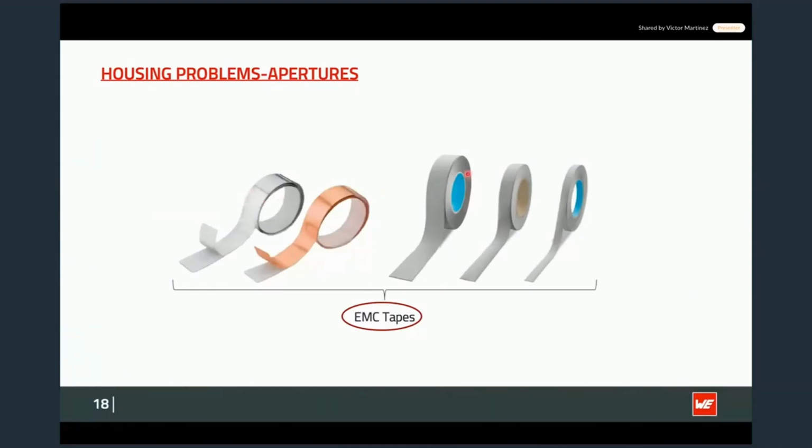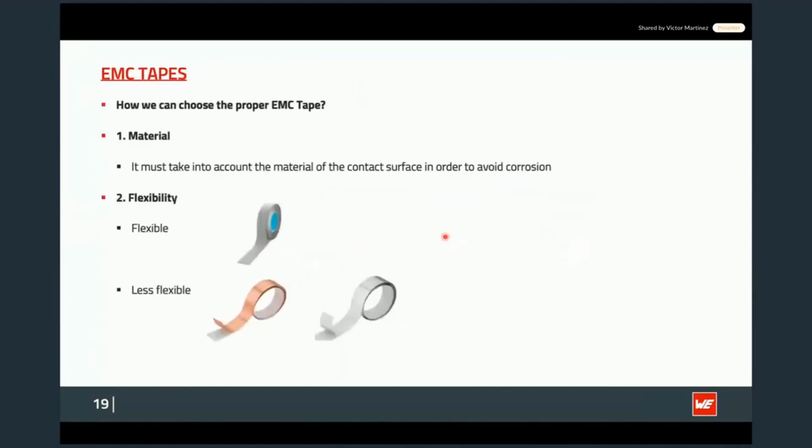Going to the other group, the textile group, we have only one available for the moment, which is the conductive fabric. The conductive fabric is a piece of cloth where the threads inside are made of nickel-plated copper, making it conductive. Then, when to use each one of them? Normally there are only two different choices that will motivate you to choose one or the other.